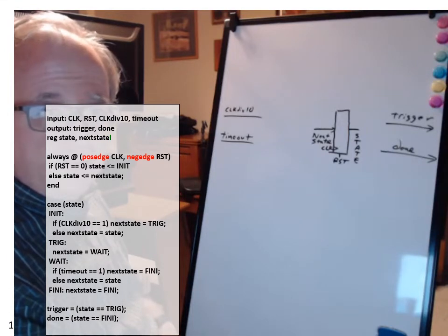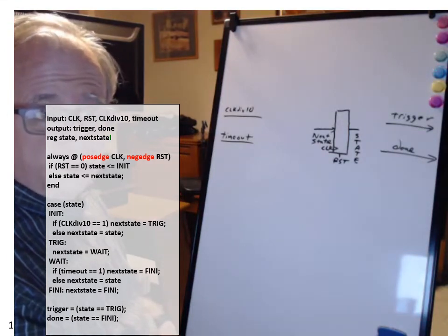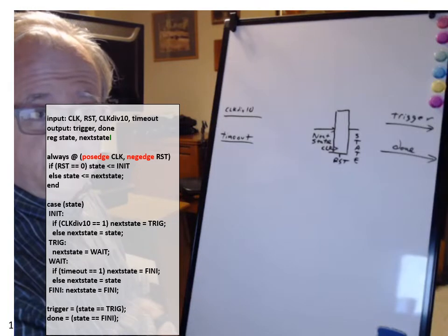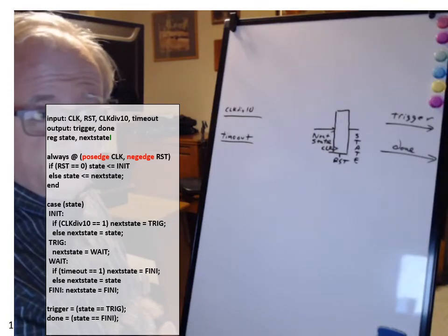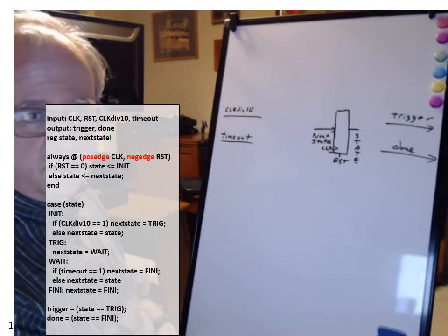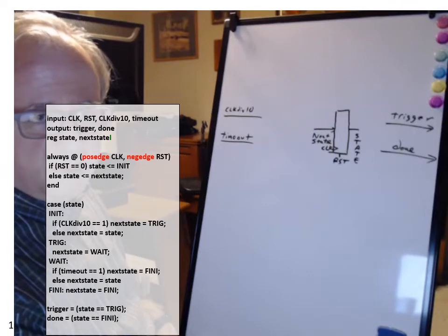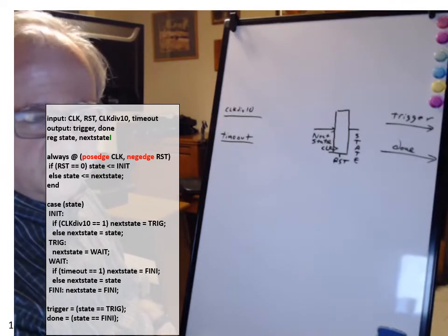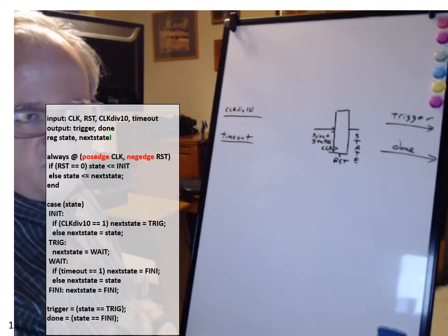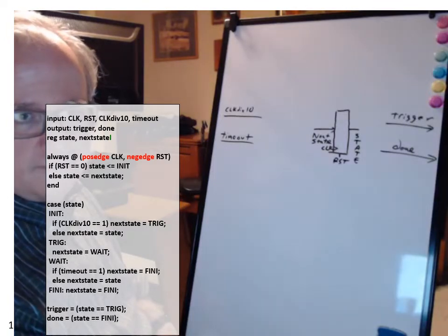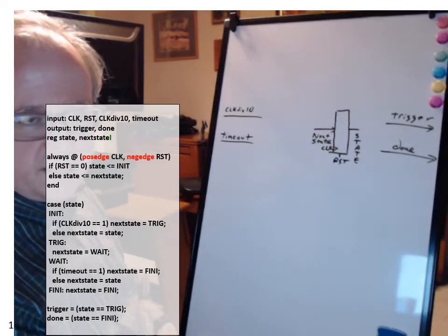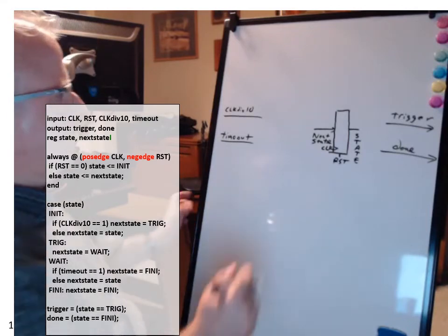You'll find that really any kind of branching structure in Verilog can be represented in a fairly straightforward manner as a multiplexer. And in the case of this next state logic, it has 4 possible branches, and it's got state as the control signal to do the selection.